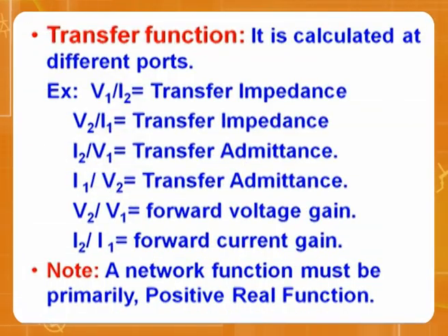Same port, it is called driving. So then transfer function can be defined in so many ways. Suppose voltage by current, transfer impedance, current by voltage, transfer admittance. It can be forward current gain, forward voltage gain, reverse current gain, reverse voltage gain, like that. Depending on the ratio, you can speak and title the name.